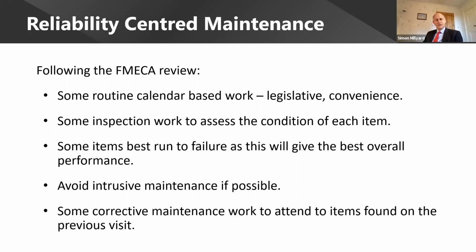And that was because at the last maintenance visit, the wisdom of the day was you put the emergency light on to permanent on, measured the current to check the current was all good. Then you put it back to its flashing code, and the dip switches had been put in the wrong position. So the wrong code was being flashed. But, you know, really, was it necessary to check the current on the emergency light when it was working? That's a matter of debate. But the end result was a maintenance-induced failure.